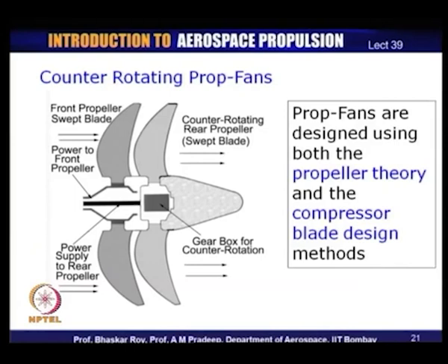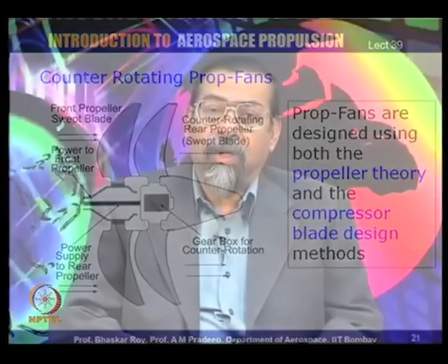So, this kind of counter rotating prop fans are indeed on the anvil, and it is very likely that over a period of next few years, we shall see many of them flying around the world, powering very large aircraft. The design of these prop fans are indeed created using a combination of propeller theory, which we have done in the course of our lecture, and the compressor blade design methods, which have been around for close to 50 years.